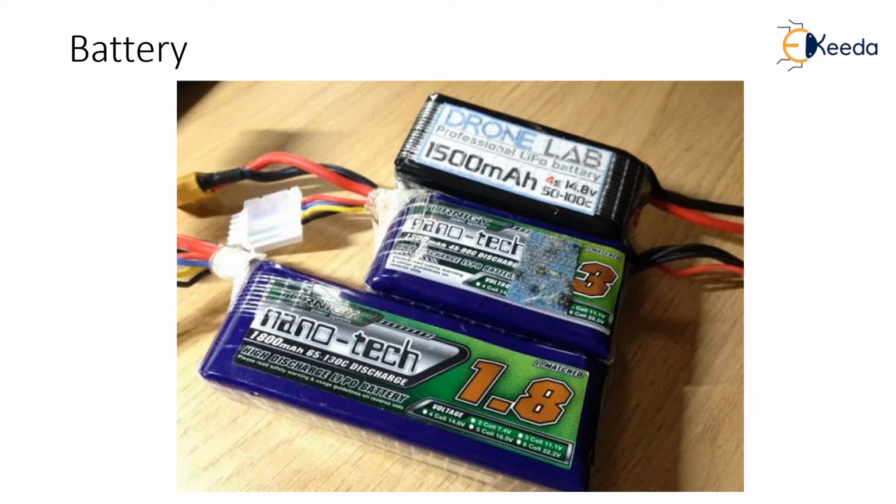the battery management system, a printed circuit board assembly that provides the intelligence of the system with features such as fuel gauging and protection circuitry, the enclosure, either a plastic enclosure, plastic exoskeleton frame, or a shrink wrap PVC wrapper, and external contacts or connectors. The main considerations for batteries are battery life, battery composition, charging, and replacement cost.